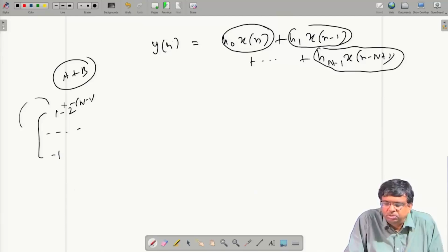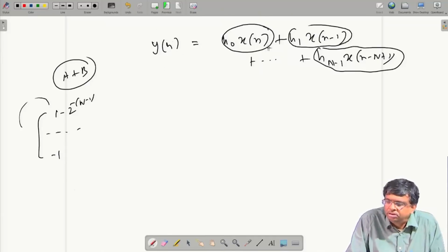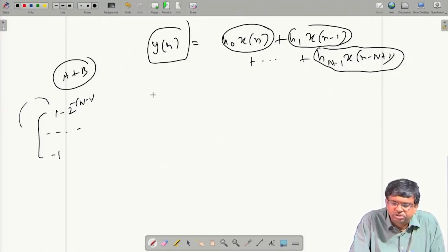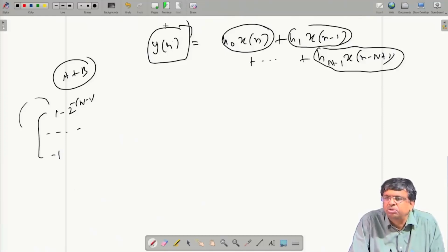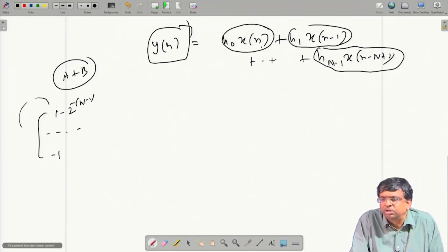Now, here what happens, suppose you are carrying out a summation like this and it is somehow told that the final summation, that is this result, is within this range for W bit representation. So, this is fine. If you give me W bits, you can always represent this nicely without any overflow. Suppose this is given to you, but look at the way you are calculating so many additions. You always take two at a time as an adder. The adder is a 2 input 1 output device, it can take only 2 fellows as input and give 1 fellow as output. Again, you take that and add with another fellow, and like that.